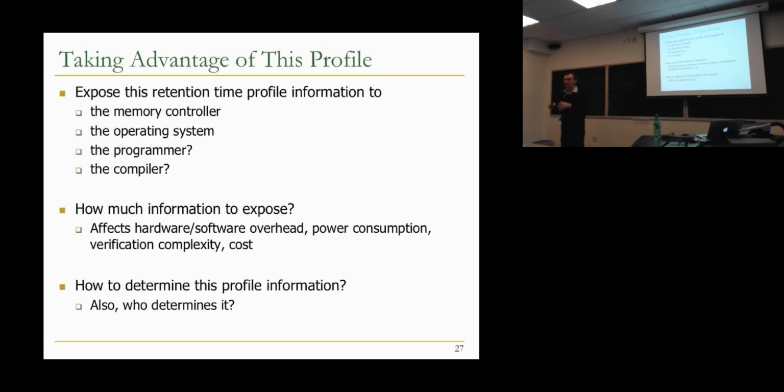And again, this is a circuit level effect. What happens is, in the access transistor, sometimes randomly charge gets trapped. And once the charge gets trapped in the access transistor, the capacitor leaks much more quickly. It turns out that this is a random process. It happens just randomly over execution time. It's very hard to control. Actually, it's impossible to control from what we know. So you really want to know the minimum retention time of a given cell to be able to figure out this information.